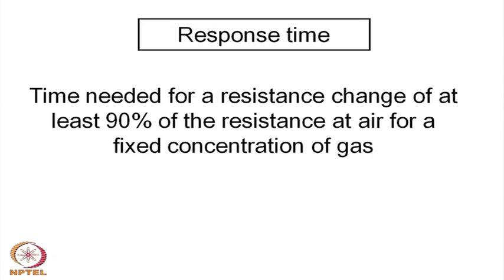It is the response time. Okay. How fast it can respond to a change in concentration. Okay. So, that is another important parameter, and the response time has basically been defined as the time needed for a resistance change of at least 90% of the resistance in air for a fixed concentration of gas. So, you introduce a certain concentration of gas and see how much time it takes to respond to that particular change.